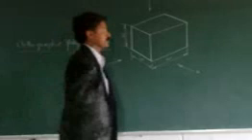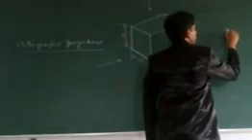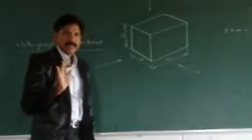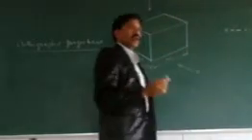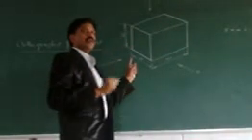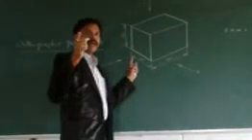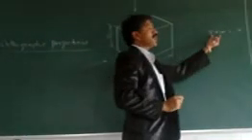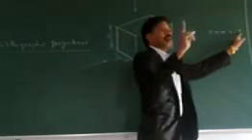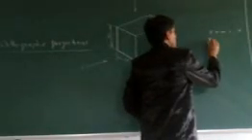Length and height. So in the front view, we should observe the length and height, only length and height. Whenever your concentration goes onto the width, you will not get the accurate front view. So in the front view you should observe only the length and the height of the object. And next come to the top view.